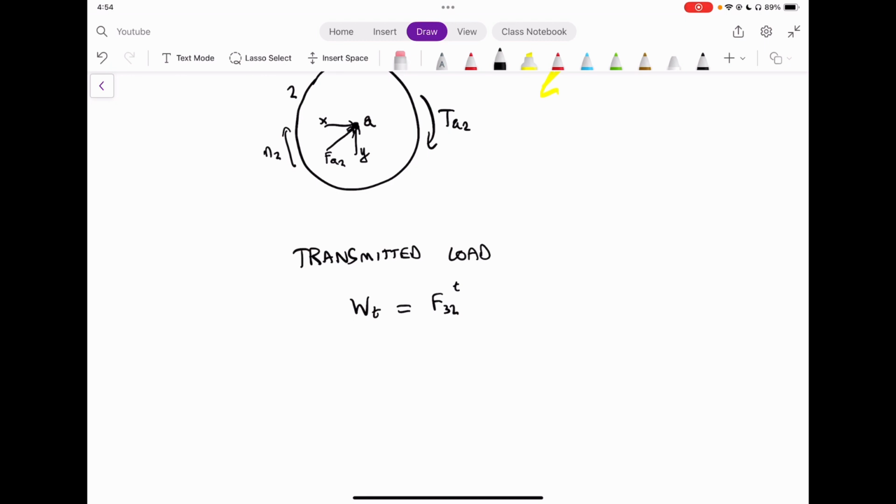And what we can write as well is that the radial component serves no purpose. So the radial component and the fact that we have an angle of attack or a certain angle doesn't really serve a purpose. The only purpose that it serves is for there to not be interference and for there to be a smooth transmission of power as opposed to just one point on the gear hitting the whole time. So that's something that's important.